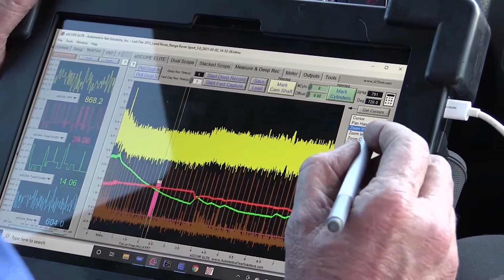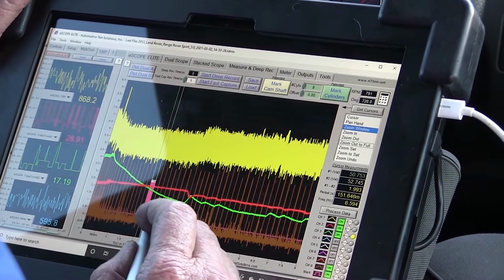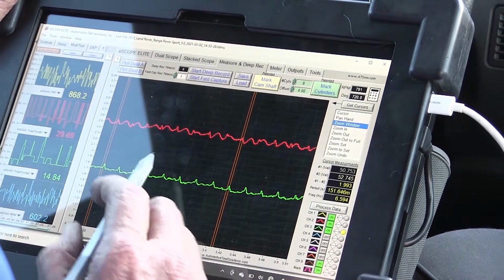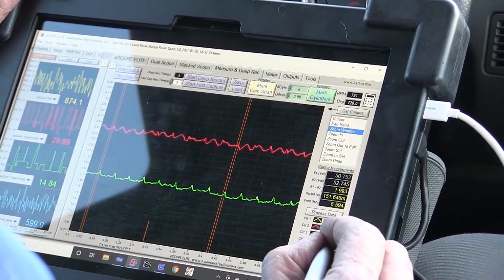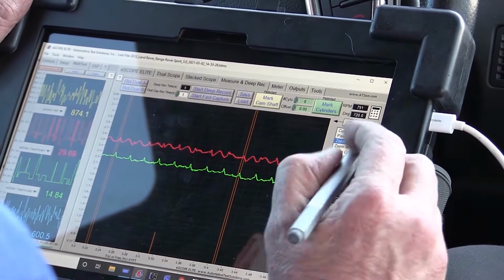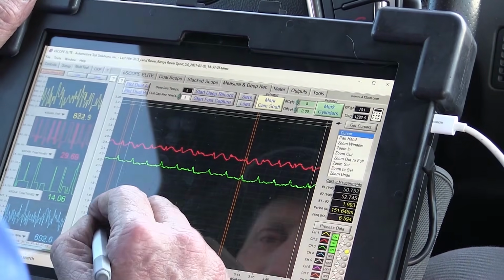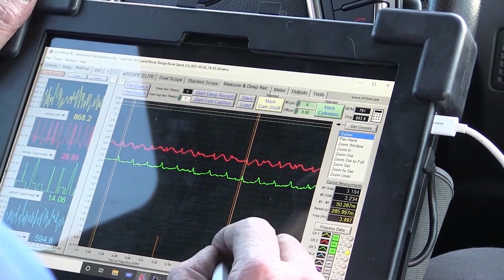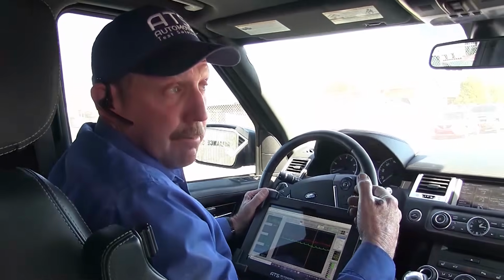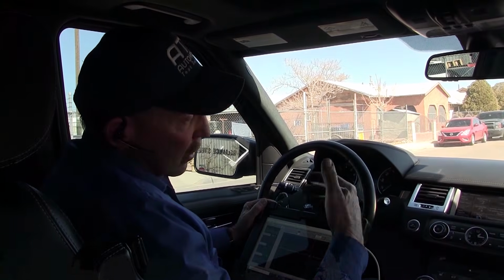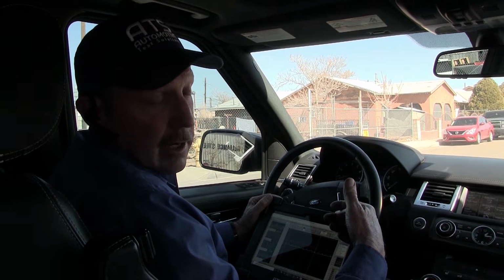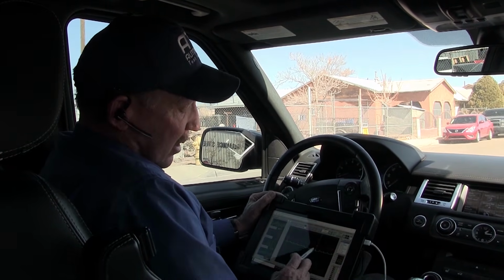Now I want to go back out, and I want to look at that same data, but move it over here to where we're starting to have our problem. Oh wow, it changed. This is so cool. I was wondering if it was going to do this. Okay, so now we're going to do the same thing. We're going to mark this off of our timing signal, our ignition, and always remember these pumps are timed by crankshaft position, whether I'm driving it by the cam or a jack shaft. It's using the timing from the crank to time when I'm turning these on and off.